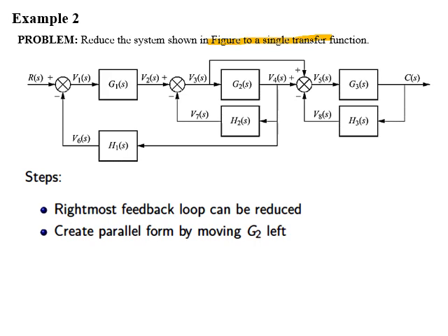If you look at the right side of the system, subsystems G3 and H3 are present in feedback form. So for its equivalent, we can use feedback form. Now, if you look at the rest of the system, no apparent series, parallel or feedback form is present. To solve this, we will use moving of blocks across a pickoff point or summing junction.